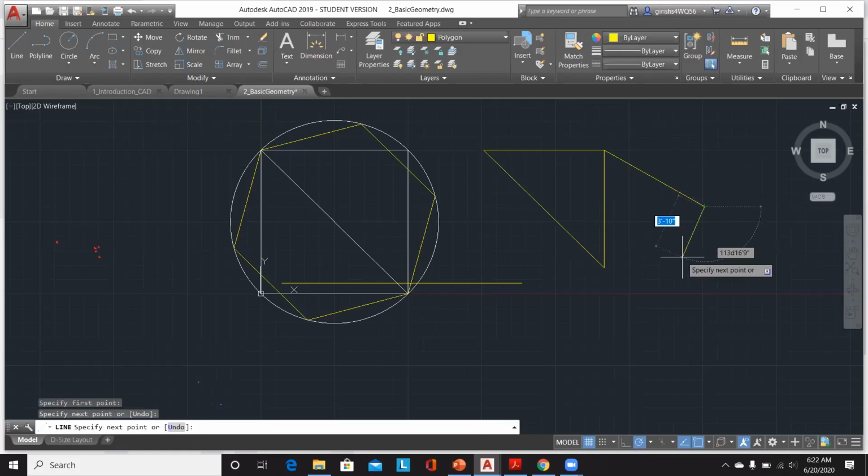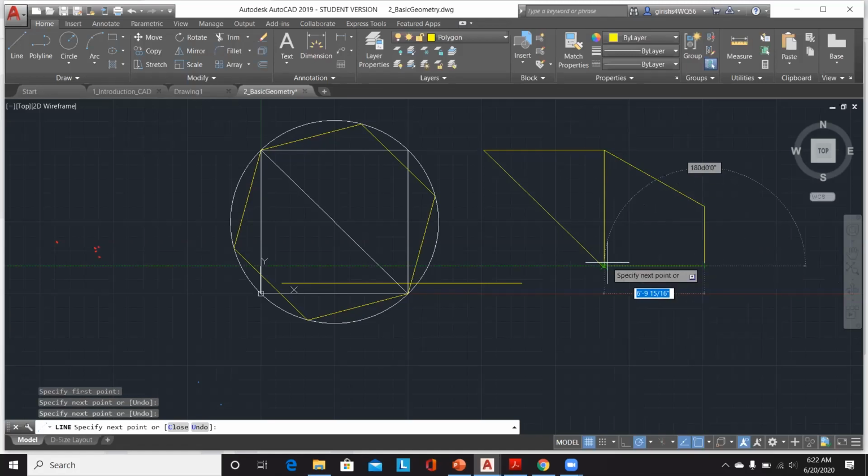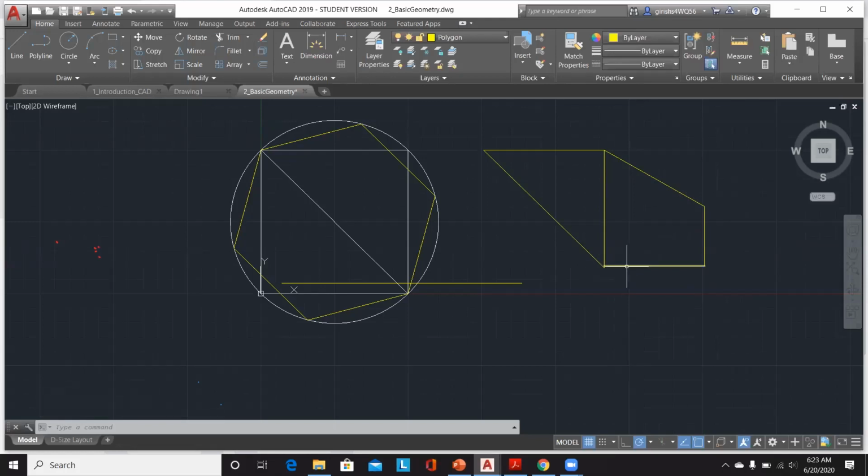So for example, at 90 degrees, it creates another angle, and then at 0 degrees, another line. So AutoCAD lets you create these line segments in multiples of a particular angle that you specify. And when we are drawing line segments, there is a hover feature that we can follow in controlling.